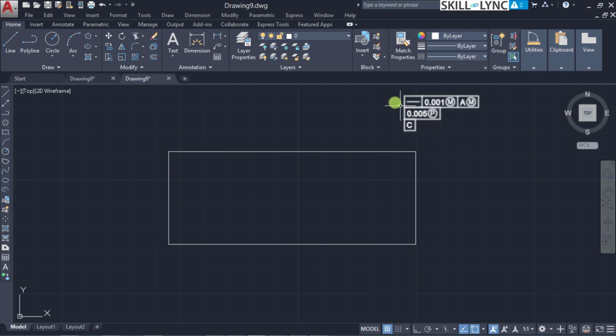Here you can see that the feature control frame is neatly positioned with the GD&T symbol, the tolerance zone, the material condition, and the reference zone, as well as a projected tolerance zone condition with its reference plane. So this is the representation of the tolerance zone feature frame referencing in here.